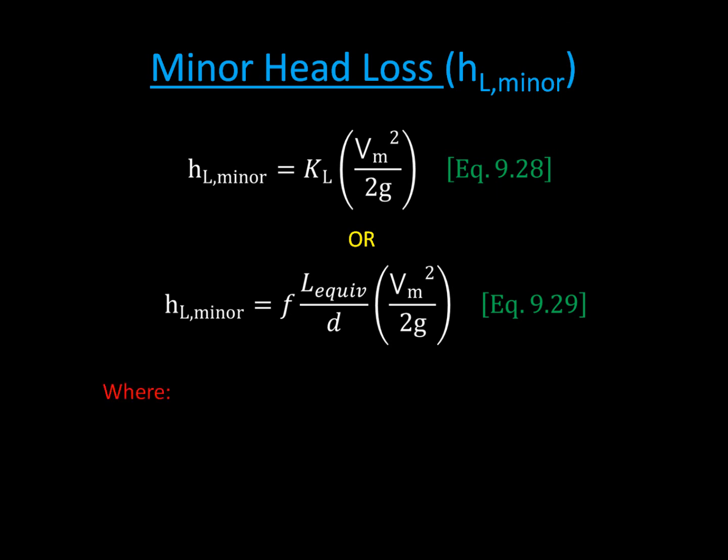And you compute that using this relationship where the equivalent length is the loss coefficient times the diameter divided by the friction factor for the material you're looking at.